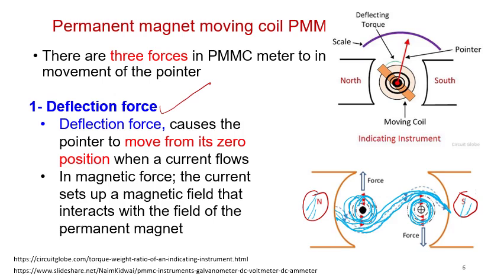It tends to stretch itself. So once stretching itself is going to push this magnetic field up and this magnetic field down. So this is a kind of simple explanation to the force generated. Again, two magnetic fields will cause force, or there is a force on this conductor. This dark is a conductor, and this is another conductor. I mean, one is going in and the one is coming out.